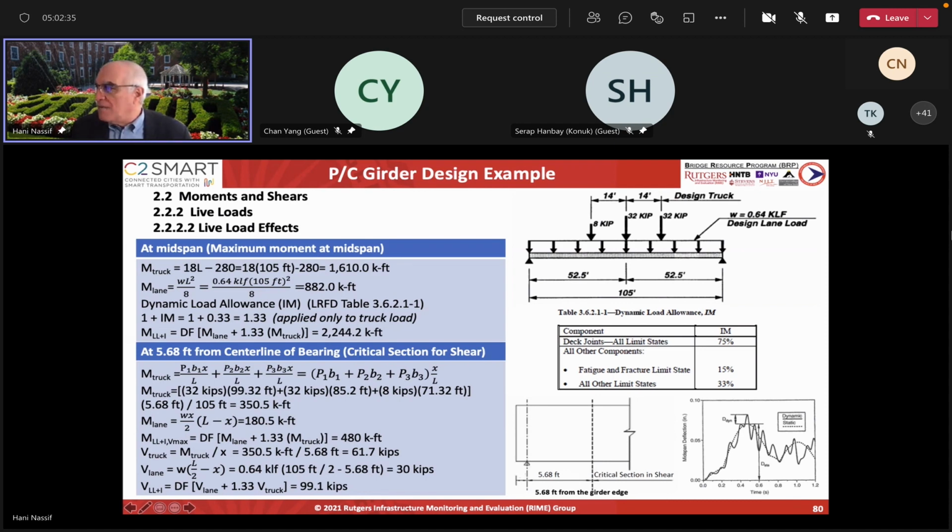Then this would be about 2.3 feet from the center line, from the middle span, would be your maximum moment, right? But the uniform load has the maximum moment in the middle. So as a compromise, the way they did it here is they place that truck right in the middle. That doesn't mean it gives you the maximum moment, but together it's easier to add them up together.